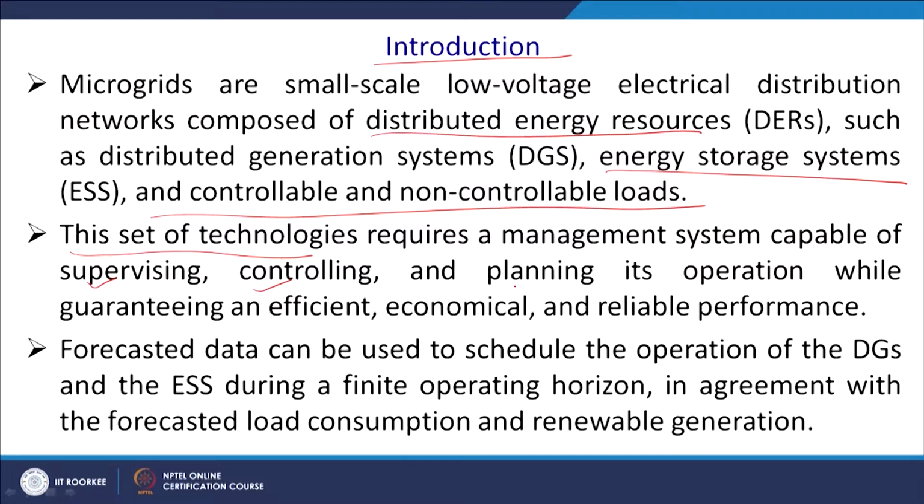So, we require to increase the state of charge of the storage element, that is batteries, to some level, and accordingly once you are in the daytime, you may have to shed some kinds of loads, and planning its operation while guaranteeing an efficient, economical and reliable performance. So, it should not have any power cuts, that is the requirement.